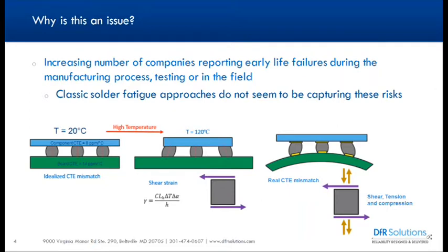And this happens a lot because it's easier to run a test on a board, because the thermal mass, the amount of material that needs to go up and down in temperature, is only the board and the components. When you have to do this for a whole entire system, the thermal mass is much, much larger because you have the case around it. That takes a longer time. So usually you try to prevent running that test as much as you possibly can, or you delay it as much as you possibly can.